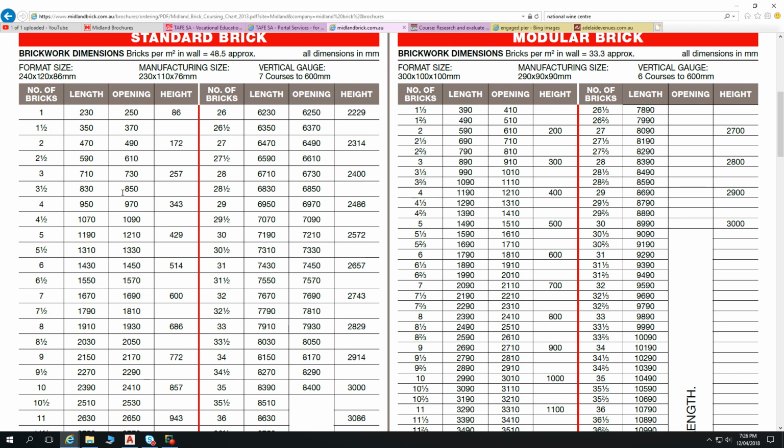When we have a re-entrant corner happening, so this is our brickwork here like that, it's happening in there. We have a 10 millimeter mortar gap here, and then our 3 bricks, 2, 3, get a bit smaller as they go on. 3.5 bricks, each with their 10 millimeter mortar gaps.